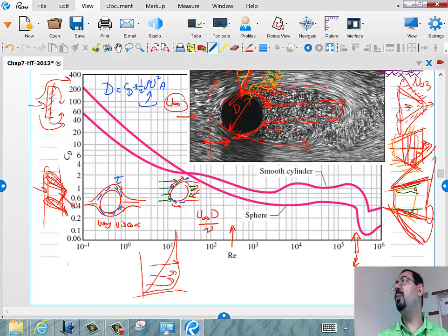So that's why they make the golf ball with all those dimples, because they wanted to make the boundary layer become turbulent. So even someone with a very weak hit who cannot make his ball go farther, they help him by making it turbulent. So even at very small velocity, his Reynolds number is 5 times 10 to the power 5. Effectively, it's as if it's really not that big. So what they do is make the flow transition to turbulence earlier. All right? So this will happen here. See, this over here, that's the transition from laminar to turbulent.